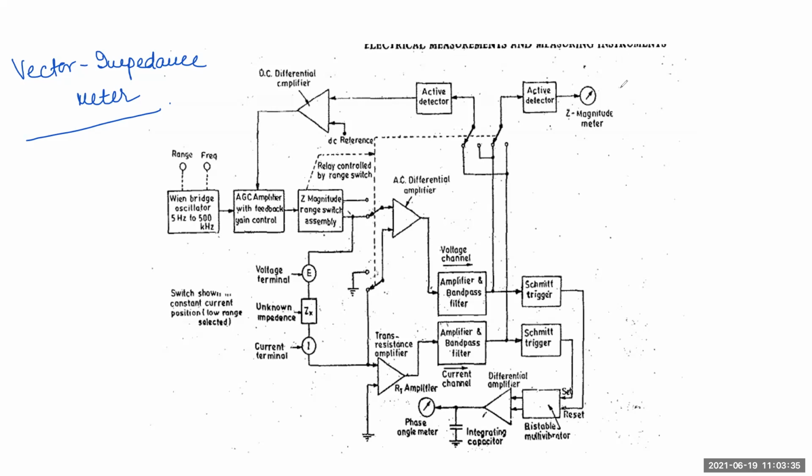Now, measurement of voltage and current is usually sufficient to determine the magnitude of impedance at various frequencies. But various frequencies also have a limit. The frequency range should be less than 100 megahertz.